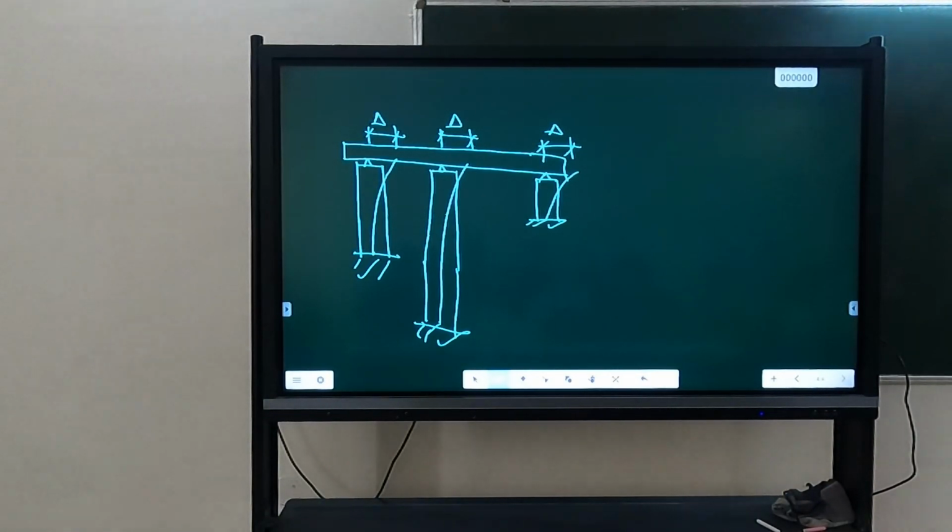So whatever capacity curve you obtain for one frame will simply be multiplied by 3 in Q, not in delta. So at any given delta, the Q will be 3 times. And in question number 4, there is a correction. It is not Q2, it is Q3.